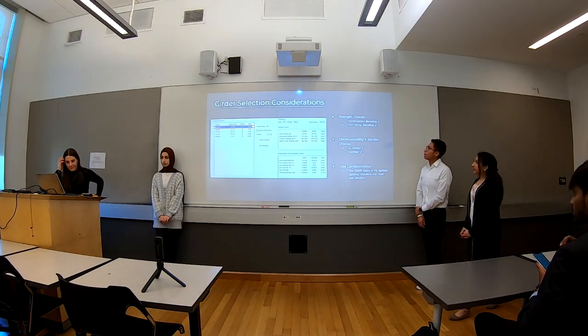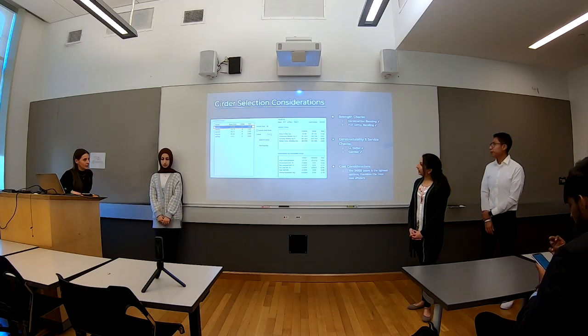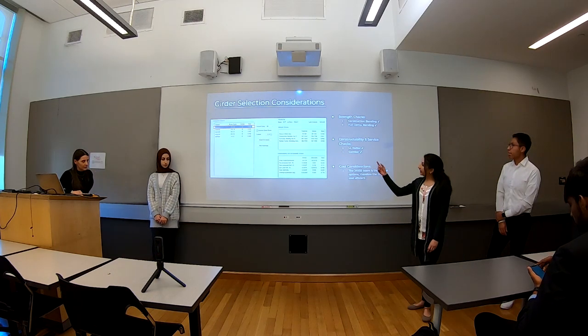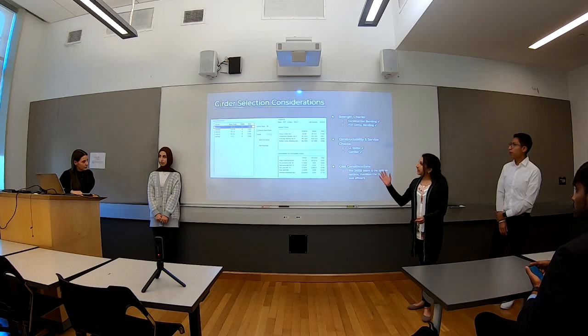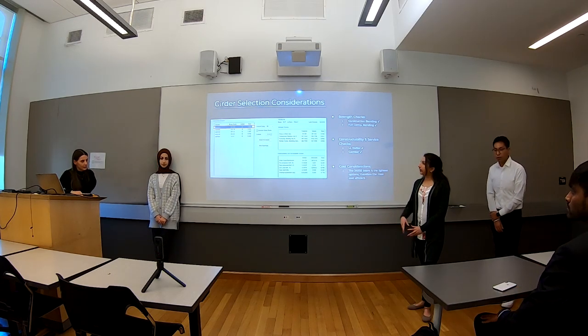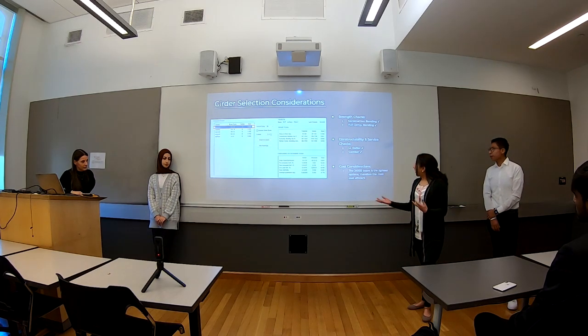Here we have the same analysis for the girder. For example, we have an example from W24 by 55. As you can see, ETABS gives out a couple variable beam sections that are applicable for the situation, but we went with the lightest one because A, it was economically more beneficial, plus it also allowed us for the ceiling height that we wanted.